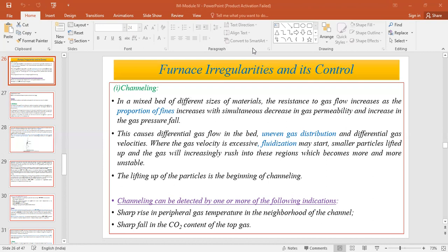When the gases encounter a high resistance, a part of the reducing gas will not participate in the solid state reduction reaction, because of which the CO generated at the bottommost part of the blast furnace simply leaves the blast furnace in the form of CO rather than in the form of CO2.